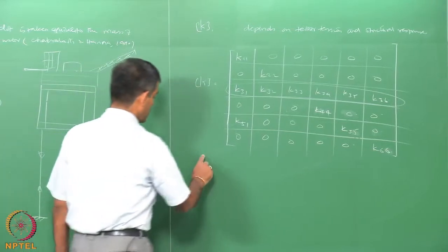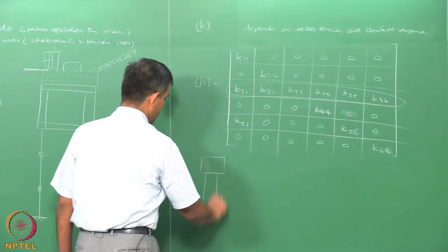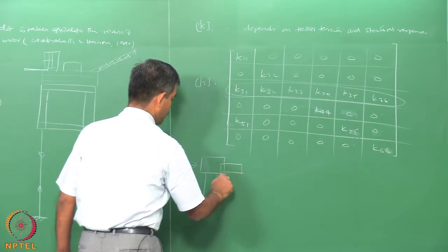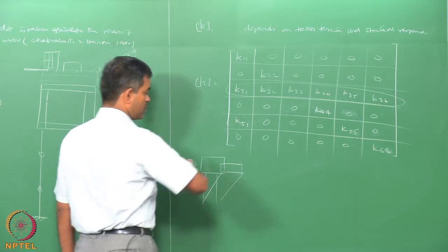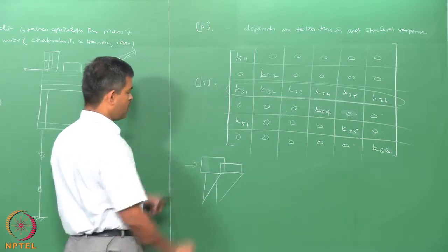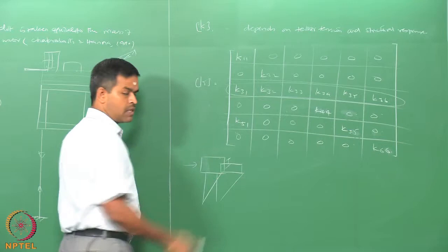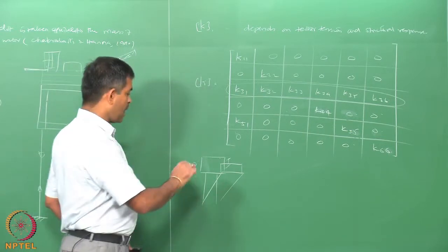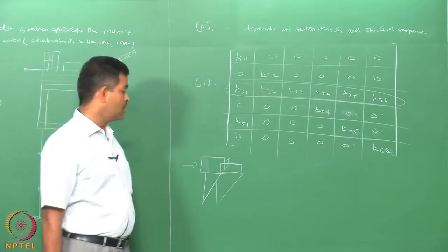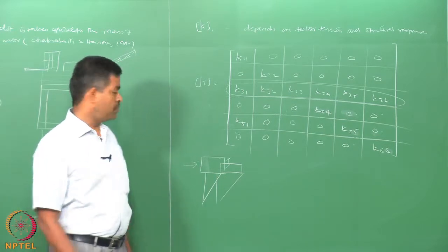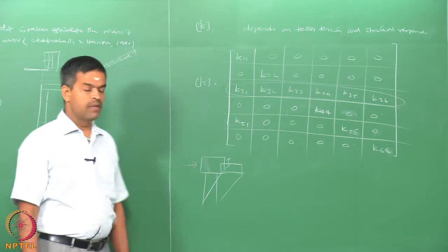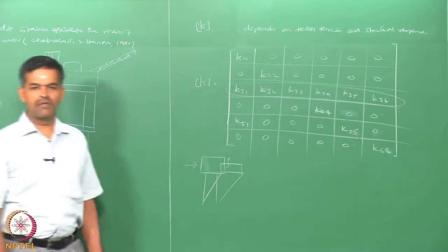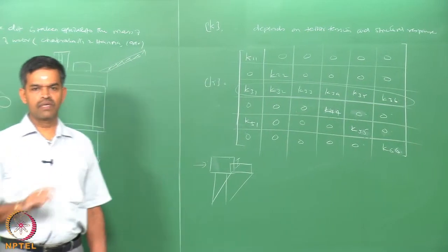It is very simple to understand that concept. In case if you have a TLP, when you give a horizontal motion to TLP, the TLP actually sets offsets and sways. When it surges or sways, of course, because of the heave movement there is going to be an offset. So, heave, surge and sway are anyway coupled. Because of the variable submergence effect, there is going to be an additional mass moment of inertia, and that is going to cause a restoring moment in the pitch, roll and yaw degrees of freedom. Therefore, heave is coupled almost with all degrees of freedom here. So, it has got a very strong coupling with all degrees of freedom in a given system.